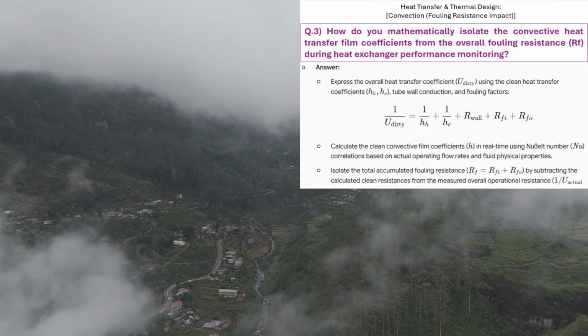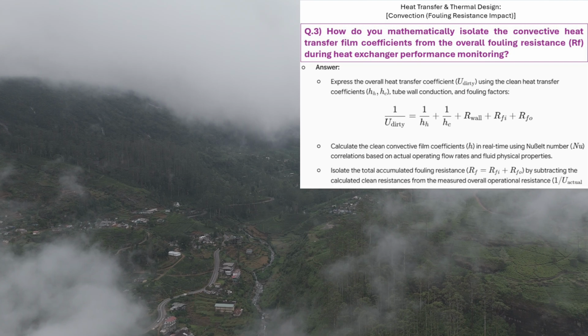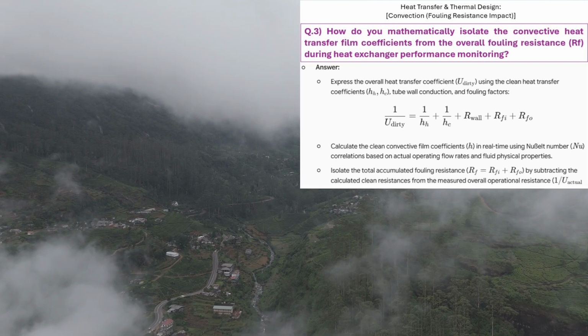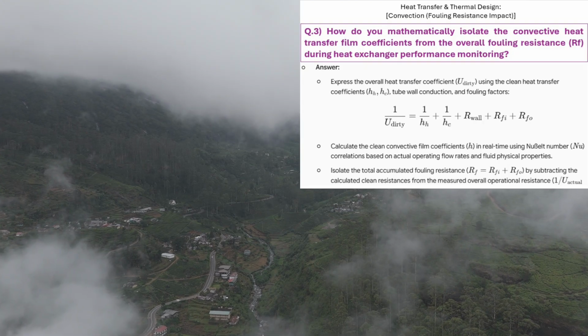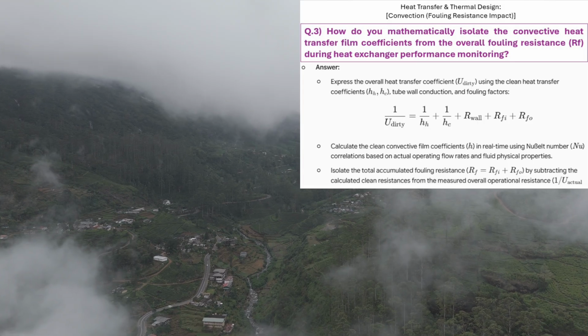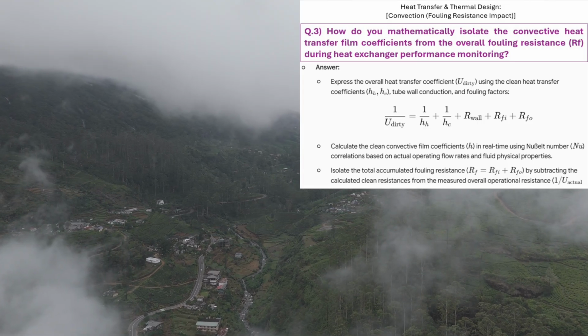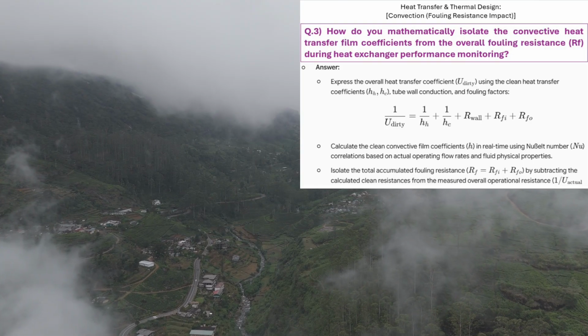Because the unit was in a turndown state. Exactly. Lower velocity means a thicker laminar sublayer at the tube wall, which drastically suppresses the convective film coefficient. So only 5% was actual fouling. Precisely. The operational misstep is attributing flow-driven convective suppression to physical thermal resistance. Distinguishing the two prevents millions in unnecessary maintenance downtime.